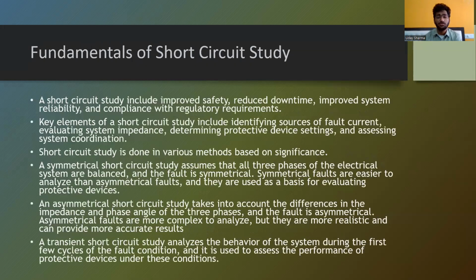Fundamentals of short circuit study. A short circuit study provides improved safety, reduced downtime, improved system reliability, and compliance with regulatory requirements. Key elements of a short circuit study include identifying sources of fault current, evaluating system impedance, determining protective device settings, and assessing system coordination. That is, in a short circuit study, firstly, we need to identify what would be the sources of the fault current.